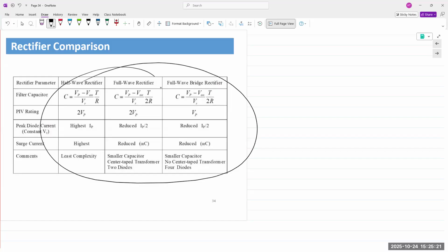It's rectified, and then the voltage is stepped down, and it's fed into a transformer. Okay, in previous supplies, we used to have a transformer at the front end. We would step down the voltage first, and then we would perform the rectification. But the frequency is 60 hertz. The transformer size is large.